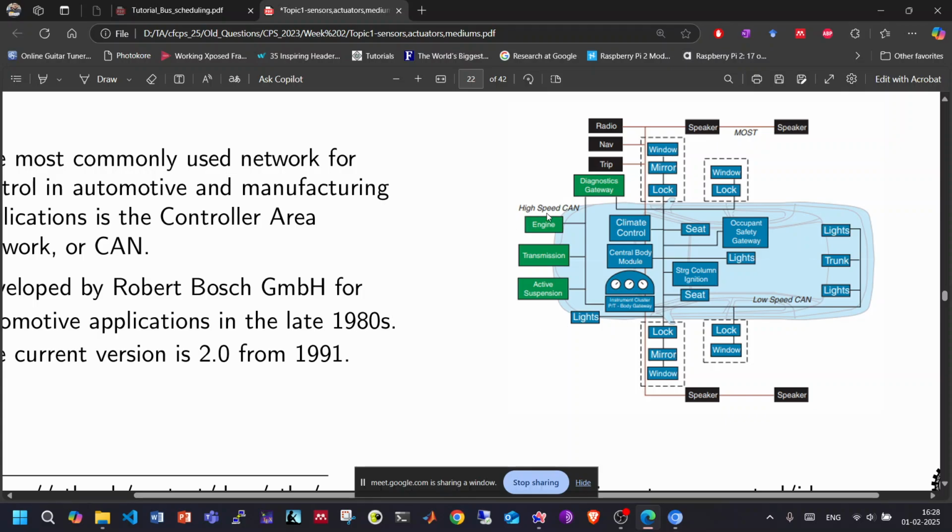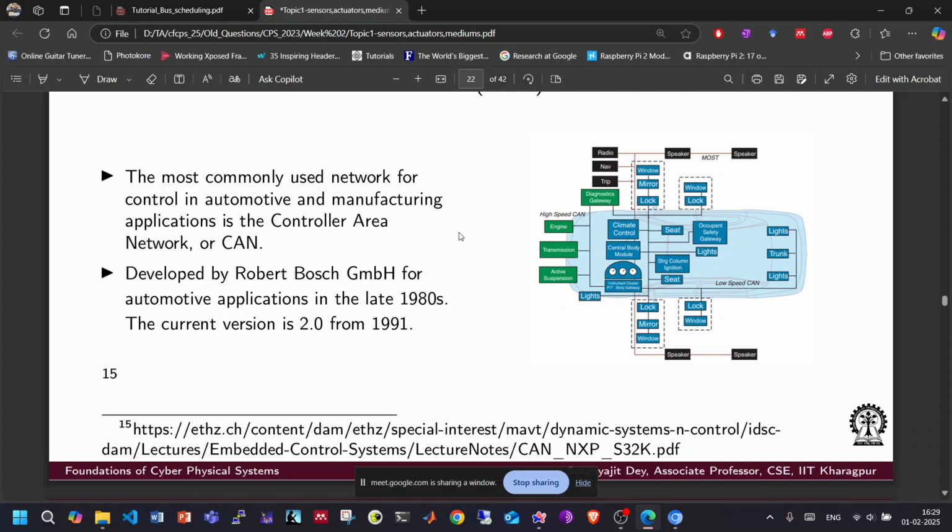As we have seen how hydraulic brakes work, there are different ways the gears, the gearbox and the other actuators work as well. I am not going into that, but what is important is how the signals are carried without any heavyweight implementation or time delay, very frequently. If you delay sending these signals, there can be a fatal accident. So to avoid that, we use a very lightweight protocol called CAN, which was first invented by Robert Bosch.